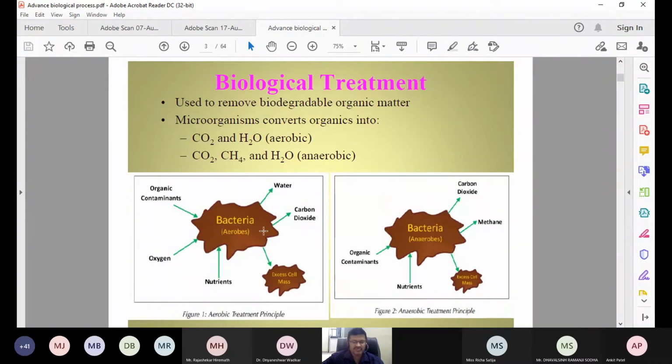After becoming 0, will the degradation stop or not? After the DO becomes 0 in the river, will the degradation stop or not? Yes, sir. It will not stop. It will go on after 0 also, and that is by anaerobic bacteria. But you know why we don't want the anaerobic condition to prevail?